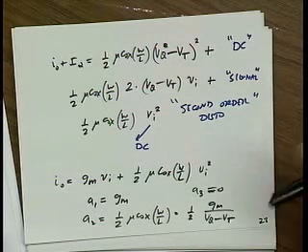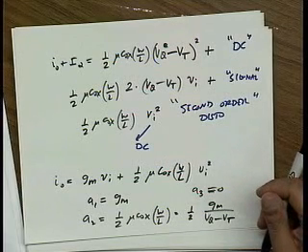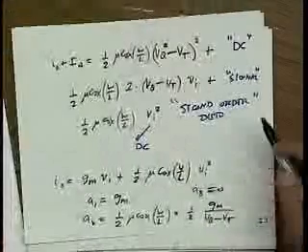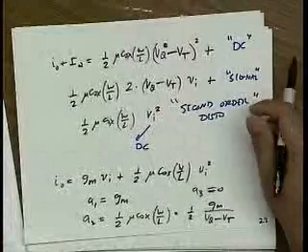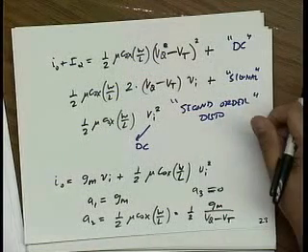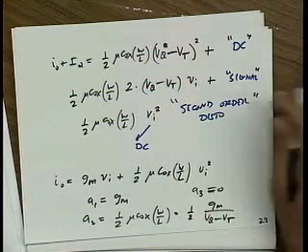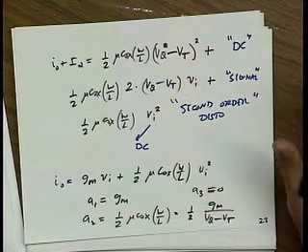Now, could someone tell me why in real life things aren't so good? What mechanisms do you think could lead to maybe some third order distortion? Okay, channel length modulation, very good. Remember, we're using this equation from a square law device. Basically, this is fantasy. If you had a channel length of 20 micron, great, you can use this equation. Even there, it doesn't take into account the body effect. So really, that equation is fantasy. In reality, it's much more complicated.